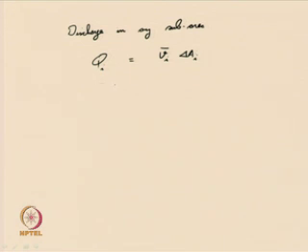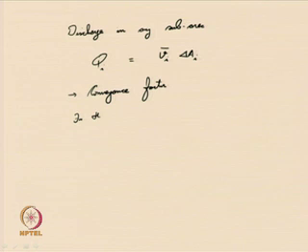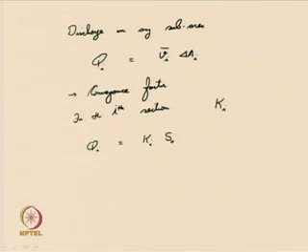So, if you are applying the Manning's equation, you have already studied the conveyance factor for uniform flow. Therefore, for the ith section, you can have the conveyance factor as Ki. You can represent your discharge Qi equal to Ki into the square root of S naught, the bed slope of the ith section.